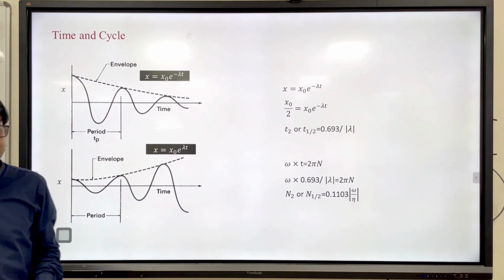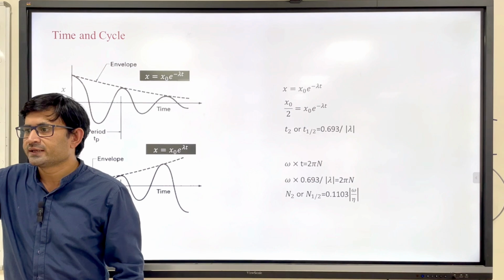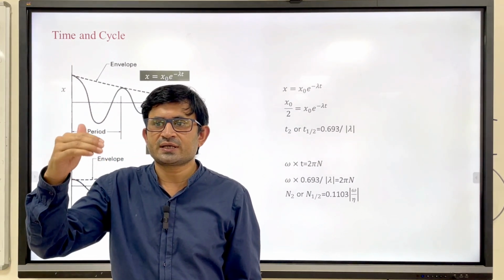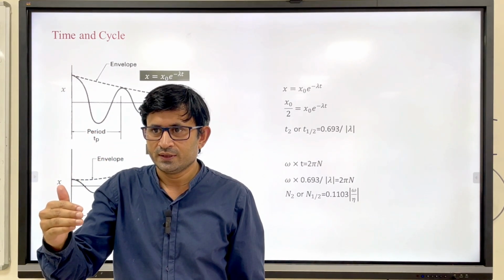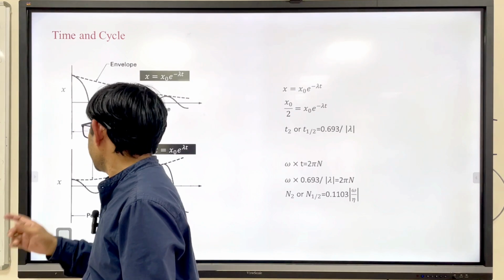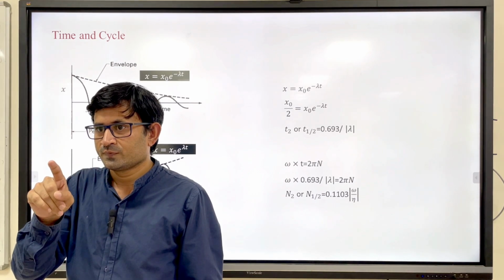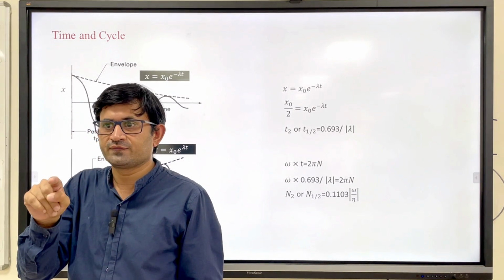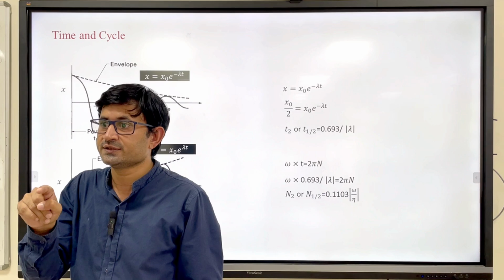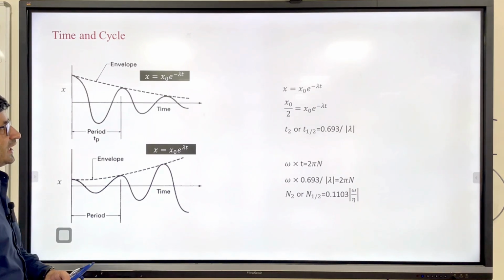Okay, so that means when time progresses, the amplitude will decrease, right? That is why we generally denote how much time it will take to halve the amplitude. If it's taking less time, that means it is fast damping. So we will see that in a short period mode case, your time to halve the amplitude is very small, and for a Phugoid case, the time to halve the amplitude is very large. Okay, and you can see how you will find it out.